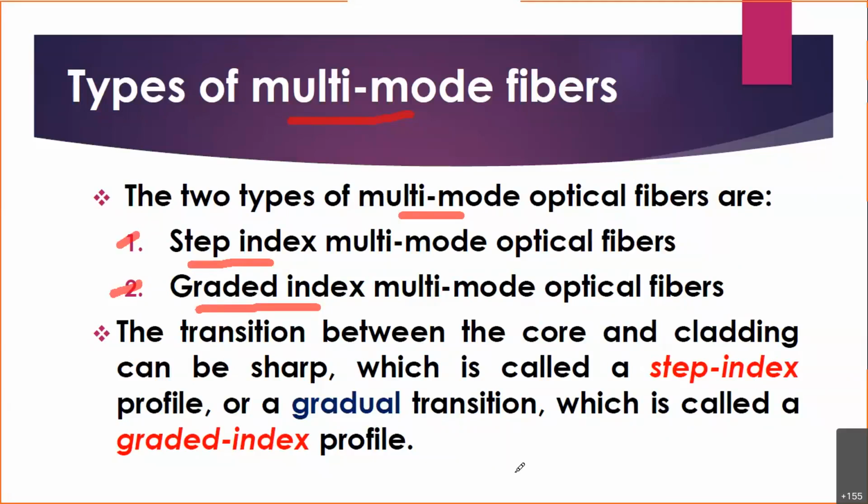Okay, refractive index is also uniform throughout the core, and in the second, your core diameter itself is changing, slightly decreasing towards the cladding side. So based on that one can classify it as step index and graded index. Why are we saying this? Suppose this is my core part, and on top of that you see the cladding.